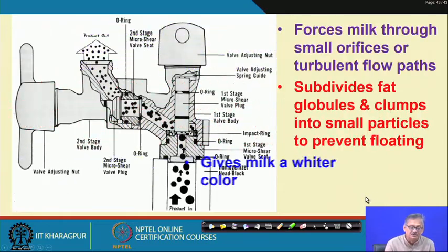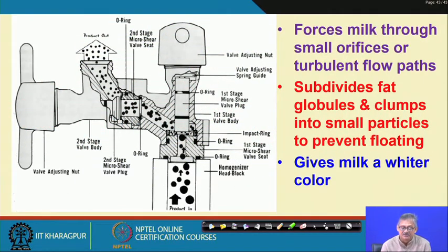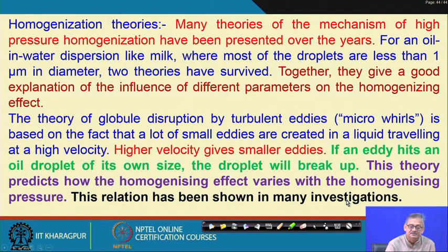So, this which I was looking for is the typical two stage valve, as we had given in figure 2. This is the first stage, this is the second stage. The milk flows through the first stage, again getting agglomerated, and through the second stage it comes to the smallest size as you have given, right. This is the two stage homogenizer valve.